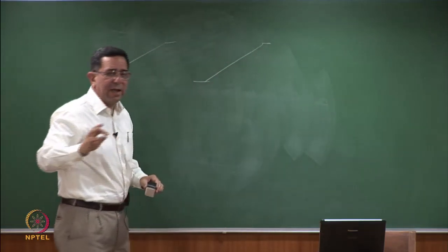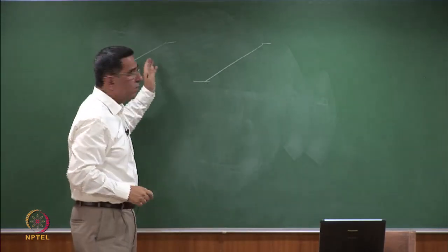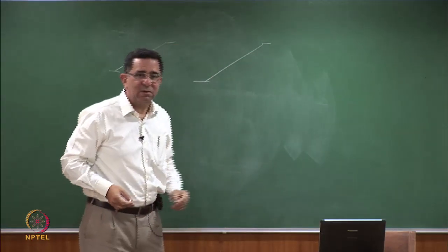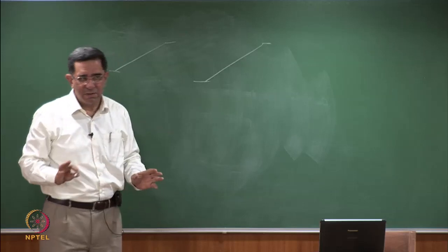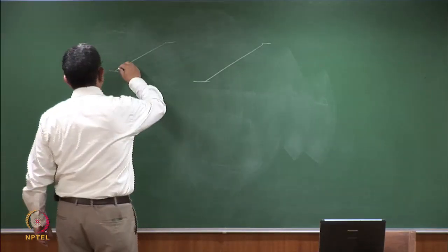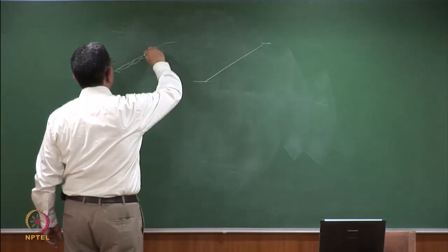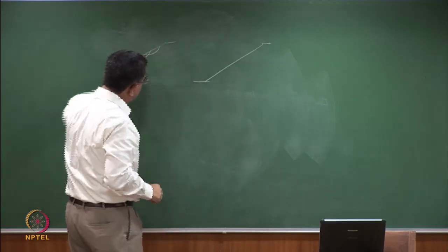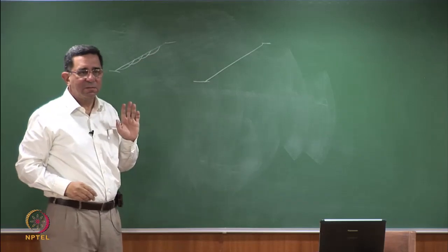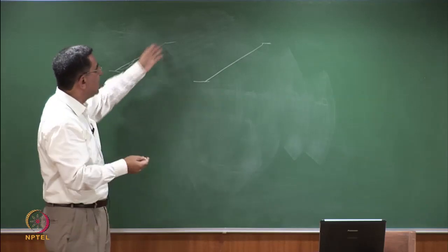Two slopes, identical angles, identical diagrams on this blackboard. Let's say one is 1 kilometer long and one is 20 meters long. Only difference is in scale. That's about it, right? And if I have this failure surface, or this failure surface, or this failure surface, as long as the strength of the material inside is the same, all of them are going to give you the same factors of safety. Agreed? Because they don't see the ends.